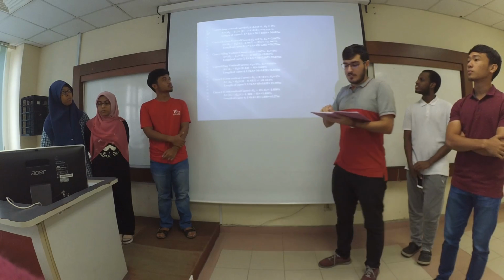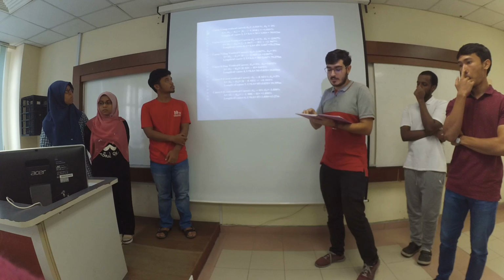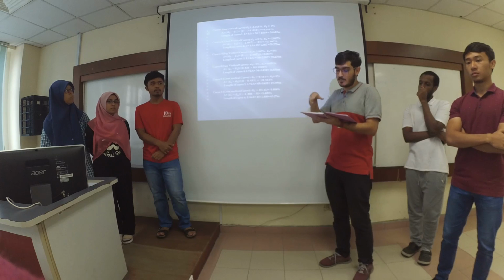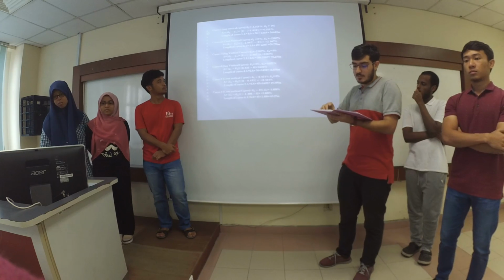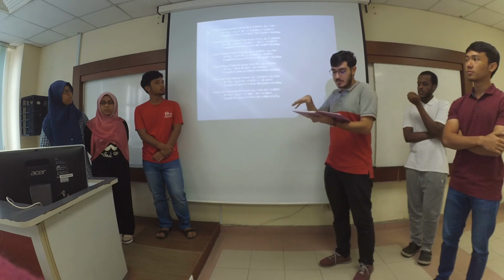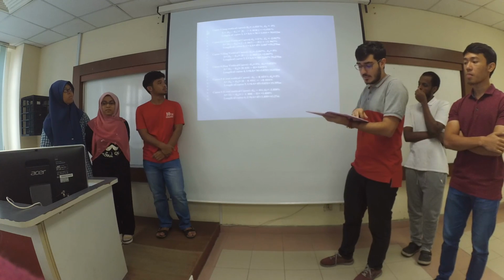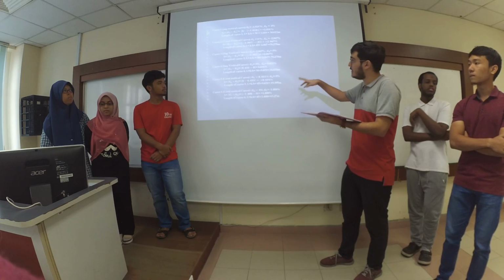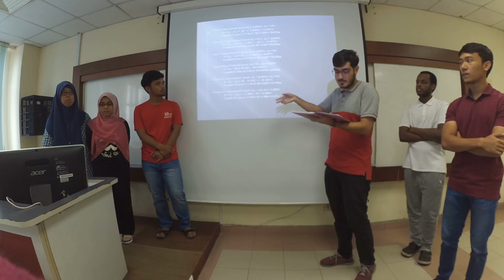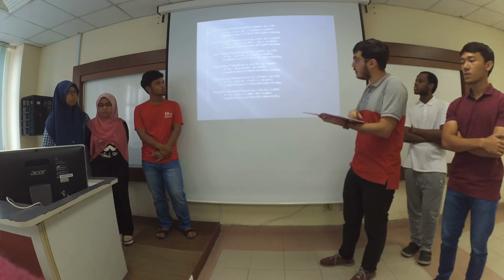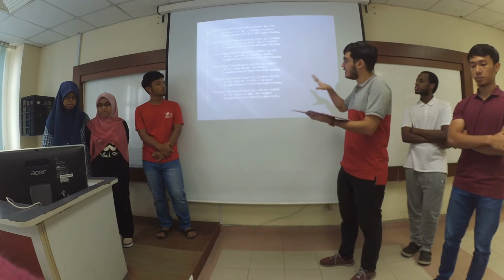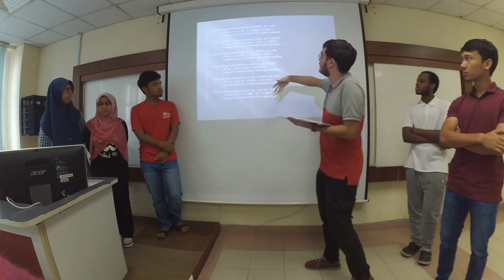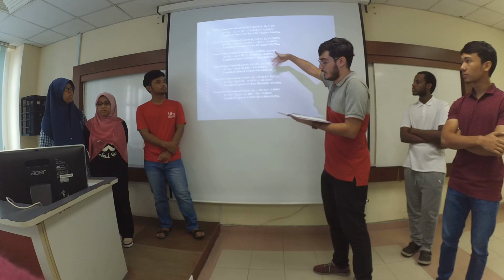Also, with the assumption of 3,000 to 10,000 average daily traffic, the road is categorized as R4. The R4 road has a medium geometric standard, intermediate trip length, and medium traveling speed. So, it is considered to be flat terrain. Referring to Arahan Teknik, the minimum design speed for this road is 90 km per hour, which we reduced to almost 60 km per hour later. The minimum K values for the crest vertical curve and sag vertical curve were recorded as 45 and 55. And this is the calculation that we did for the length of the curve based on the K value that we calculated.